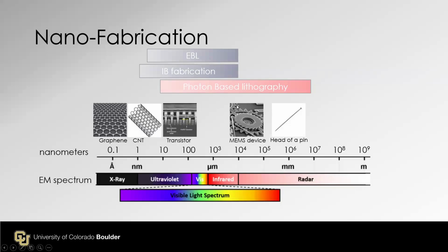In practice, it is easy to do 10 microns, 100 microns, no issue, but going down to making a 1 micron by 1 micron square with a contact printer optical lithography system is a little bit challenging. So E-beam lithography comes in to cover this range, 10 microns and smaller, and now we can go down to 5 nanometers or so.